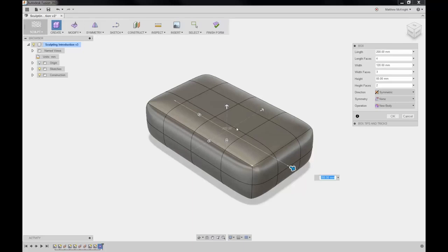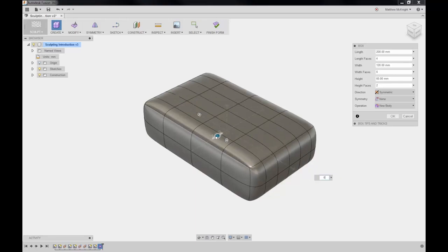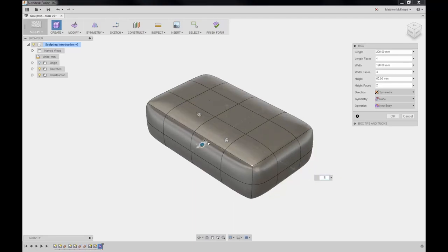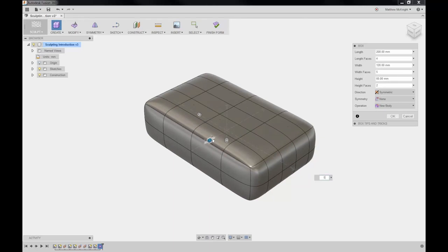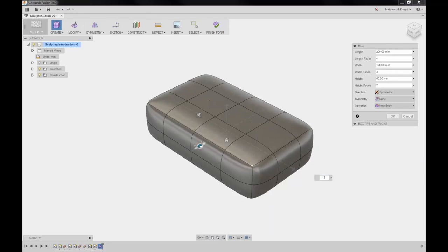The other thing that you'll notice is that this box is actually divided up into sub-surfaces. So you can see here, and these are all the T-spline surfaces that are creating the box. We can subdivide that surface up into more T-spline surfaces just by sliding the little manipulators on our triad here. So I can add additional or remove additional faces by manipulating this geometry very quickly and easily.